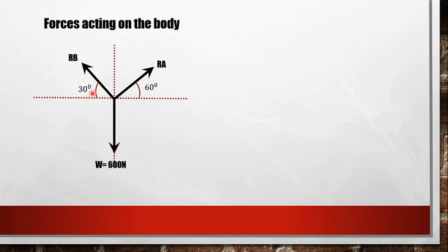Now, in the force diagram, we have three forces acting at a point, that is at the center of the sphere. As we have three forces, we can apply Lami's theorem. Remember, Lami's theorem can be applied only to a force system with three forces acting at a single point. In short, it is applicable for coplanar concurrent forces. So let us apply Lami's theorem.